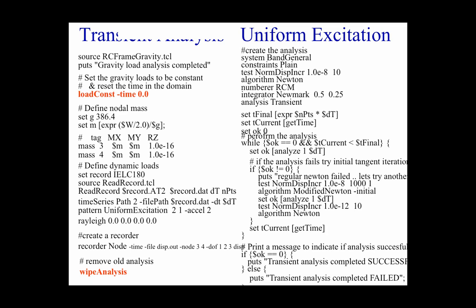And then the command is an option to reset the time in the domain back to 0.0. Basically, so you don't miss the first couple of points in the earthquake excitation. Pretty much all these other commands we've seen in some of the other examples I gave.